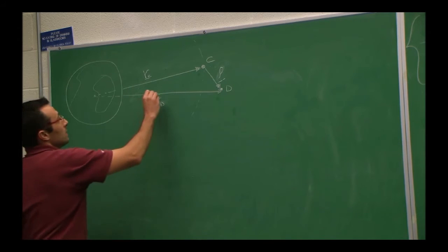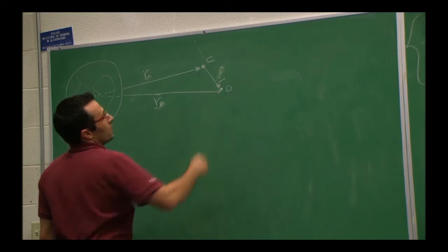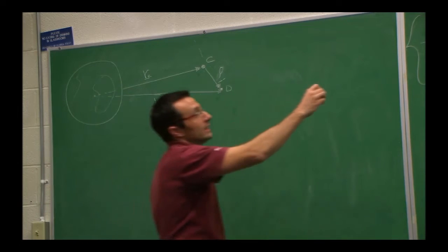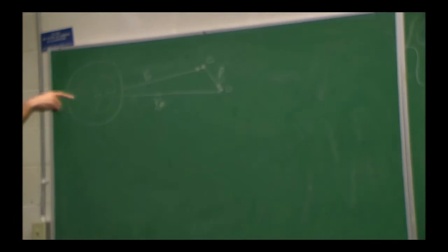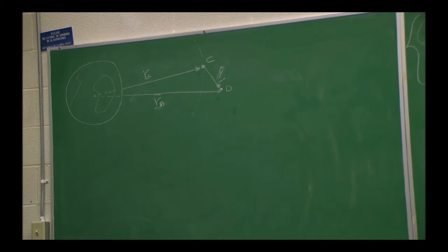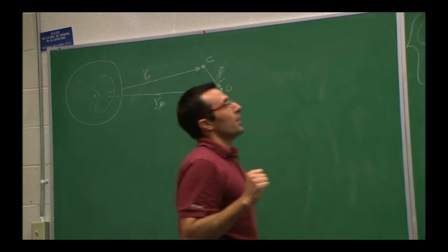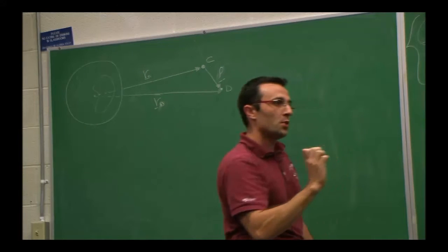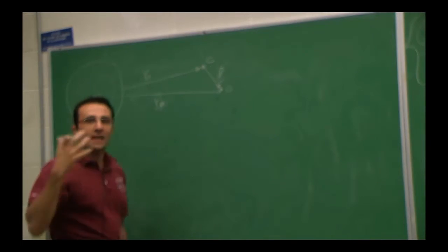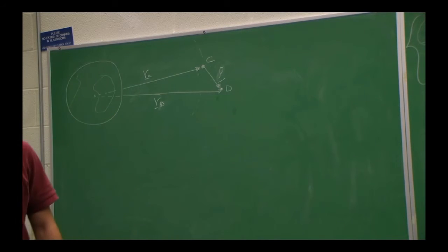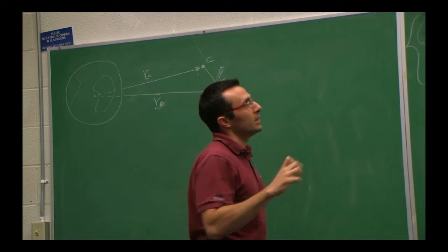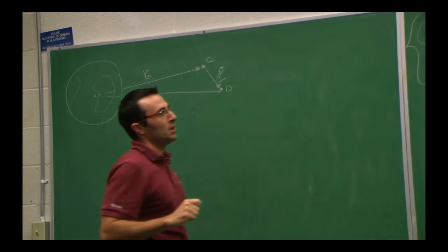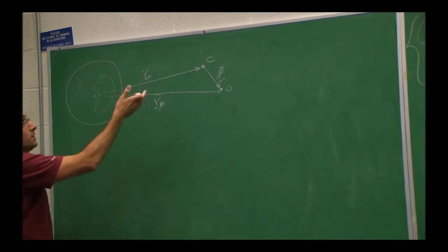Why? Because again, if I can put the evolution of this vector in some kind of state space form that looks like this, well, this actually has an analytical solution. You can integrate those equations numerically or not. It's analytical. You can, as we will do, derive impulsive maneuvers that go from where you are exactly to the chief analytically without doing any numerical iteration. Even continuous control, when you have a thruster that turns on and stays on for a while, can be solved kind of easily. When things are linear, they can be manipulated pretty well. So that's why people do it, and that is what you have in reality.